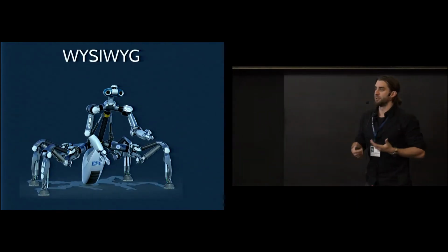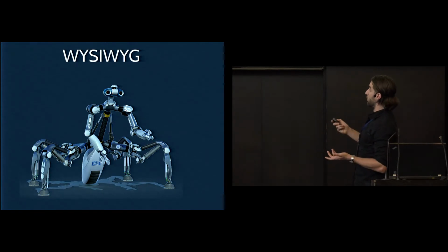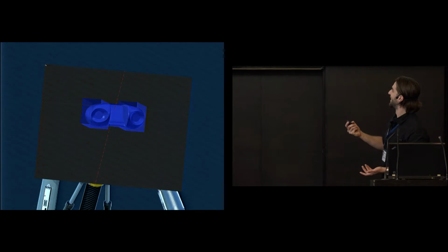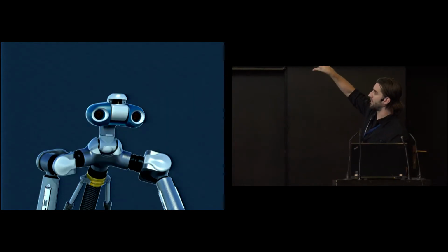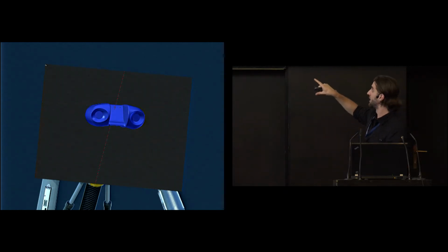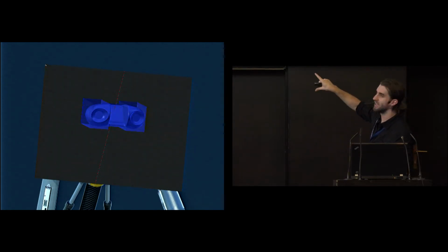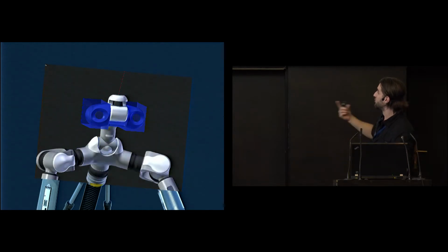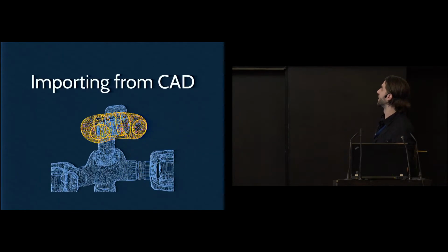And so what you effectively get when you work in Blender to create your UDF models is a what-you-see-is-what-you-get experience. You start with your robot, and whether you build it from scratch or you get it from CAD, you can then import it into Blender. You separate the visuals you get, because that's the actual geometry of the robot. Then you can create the collision objects using the bounding boxes of these visuals, and you can even refine them, creating multiple collision objects depending on how detailed you want it. Then you have the final model, and what you see in Blender is exactly what you're going to export and later use in whatever tools you want to use UDF with.